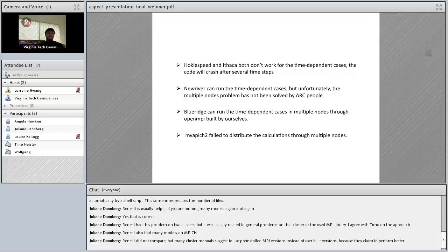Everything works well with Cartesian models, but as soon as we go to spherical, even a constant viscosity case without a very difficult setup, we're immediately having trouble with convergence. I don't know how many people have been running spherical models and if there are any tricks there that we're not aware of.